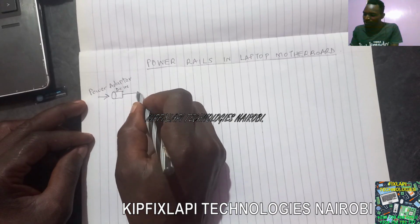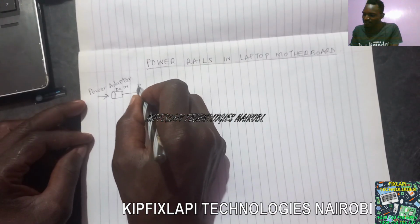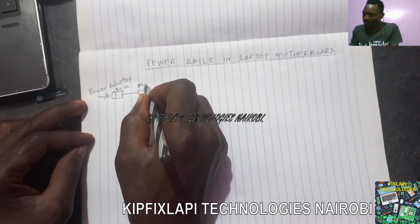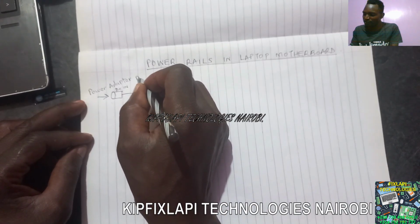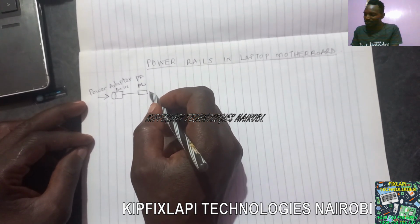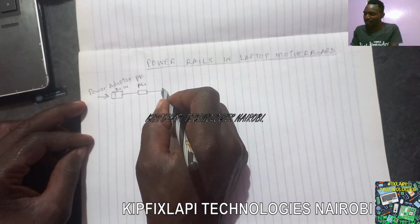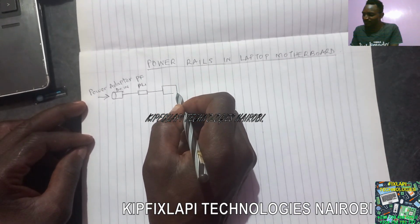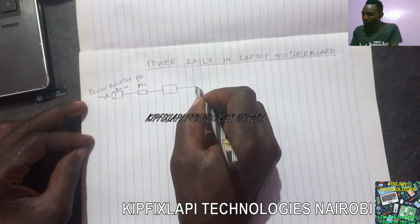After the power port, we'll have a component called the PL, or the power inductor. You will find it written PL1. For some laptops, they use PF for power fuse. So if you find PF or PL, that's one and the same thing. After the power inductor, we'll have the first MOSFET. We call it MOSFET 1. Then after MOSFET 1, we'll have MOSFET 2.